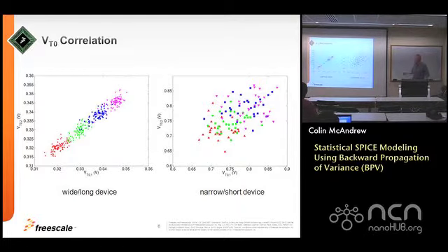So there were 17, and I've deliberately chosen the 4 wafer lots that, for the wide long device on the left, have the greatest spread in them. So you can see that there's a significant variation here, and there's essentially almost a linear correlation between those. And what that indicates is that the threshold voltages are moving together. So variations are correlated, and it's coming from global process variation, which is the overall variation in quantities like the substrate doping and the oxide thickness between wafers, between lots, and it could be between manufacturing sites, but here it's just between lots. They were manufactured in the same plant.